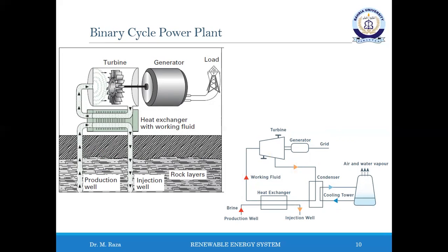point. For geothermal fluid temperatures below about 170 degrees Celsius, higher generating efficiency is possible than in low temperature flash steam plants. A disadvantage is that keeping the geothermal fluid under pressure and repressurizing the secondary fluid can consume some 30% of the overall power output of the system because large pumps are required. Another disadvantage is that it requires a large volume of geothermal fluid, for example, around 700 kg per second, to produce about 29 megawatt electrical power.